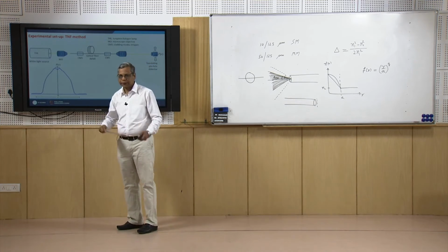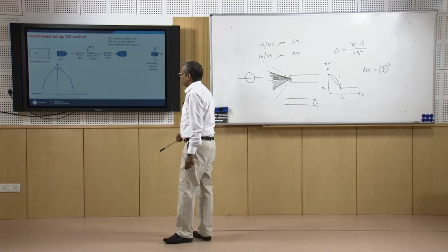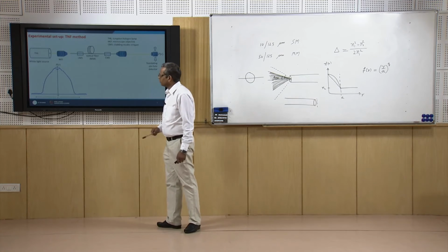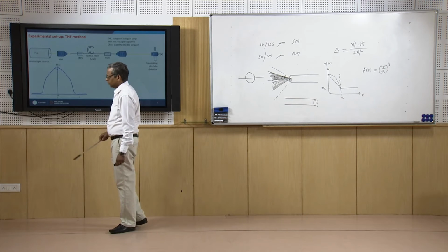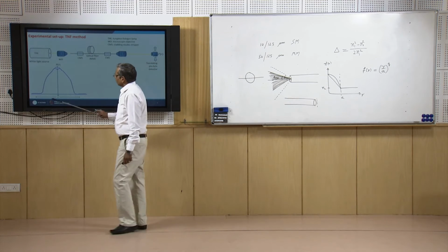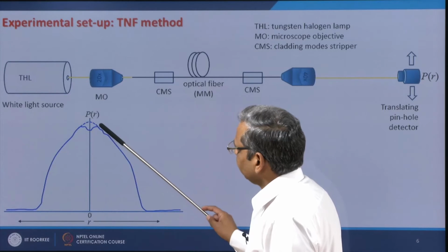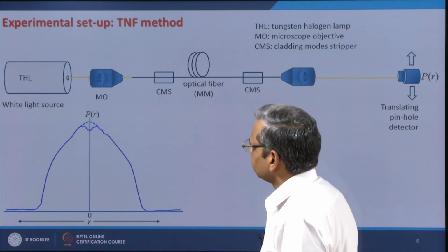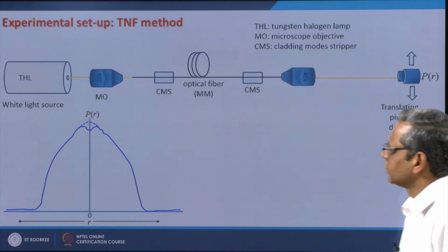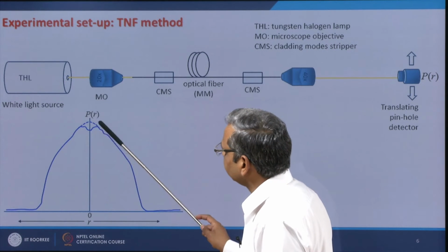When you raise the temperature to a very high value to collapse the preform, there is germanium out-diffusion, and because of that there is a small dip at the center. So, I can correct it by extrapolating or interpolating like this, or by leaving out these points and extrapolating.